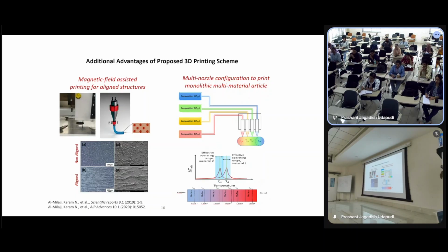So I should have made a larger video. But anyway, here this is inkjet printing, and this is direct ink writing. Although it's ink writing, it makes 3D structures because we use slurry material, and it also evaporates immediately after printing. And again, this is what I talked about, compositional grading. We can use multiple nozzles to have different grading, which will lead to different functional grading.